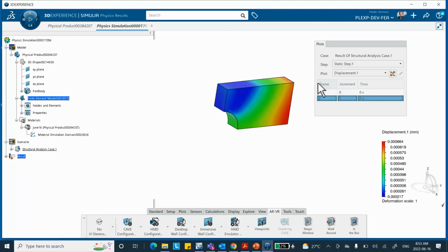You know, I took half of the model, I have to take half of the load. Look at your problem. You had 4,000 pounds applied here. You divided this into 8 pieces. Now this 4,000 pounds is applied only on these four faces, 1/4. Okay, good. Any questions? Any other questions here?